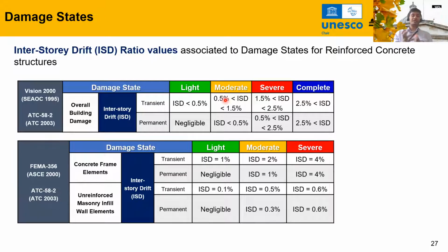So we need this engineering parameter, that is displacement or deflection, for example the roof displacement or the inter-story drift ratio. Those limits we need in our mathematical numerical analysis. Different codes or standards recommend these values, or you could go into the literature to find these limits or thresholds for the different damage states for the particular building types that you are interested in.